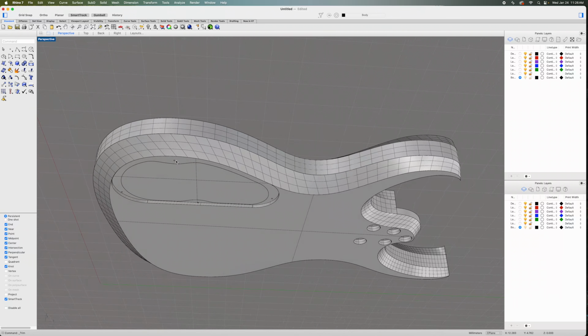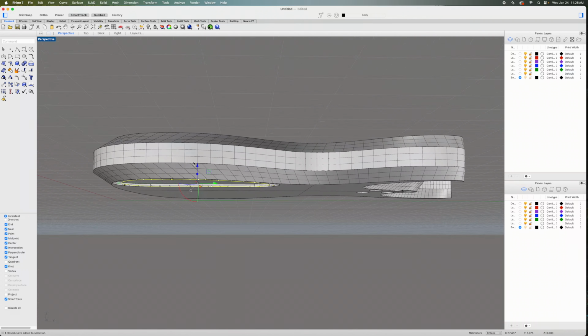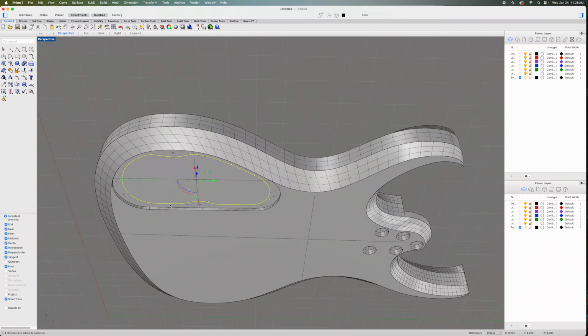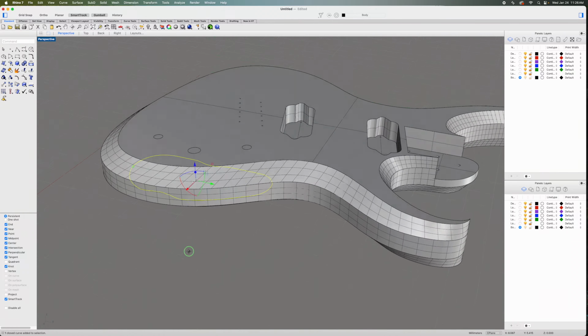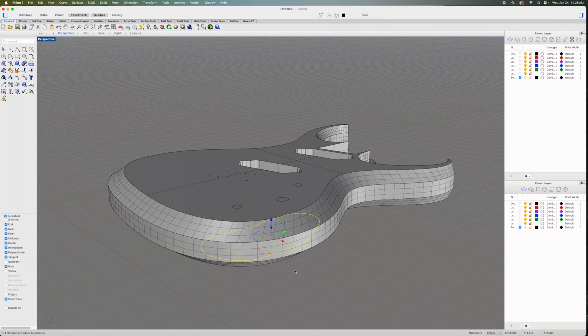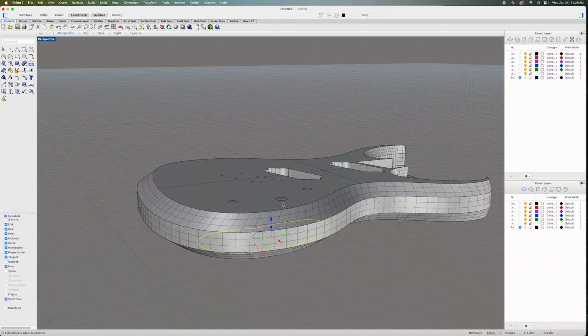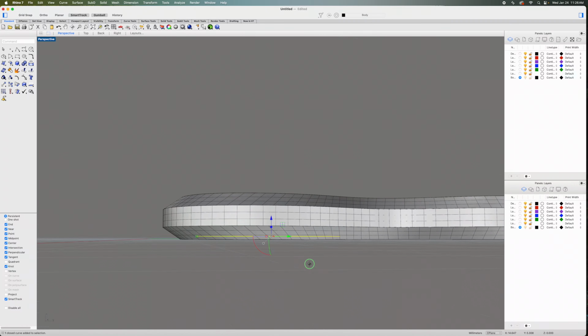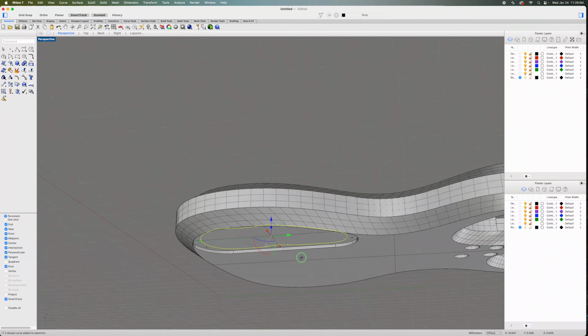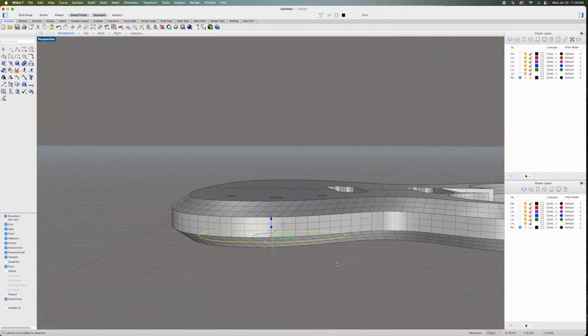So now what I need to do is select the elements and then raise those up 0.125 inches. Now I'm going to select this element, and I have to extrude it straight up to a depth that places the bottom of the cavity just below the surface, about 1/8 of an inch below the surface. So I've already raised that element up 1/8 of an inch. So I have to subtract 1/8 of an inch from 1.75, which is 1.625. Then I need to subtract another 1/8 of an inch, which represents the thickness of the top. So it becomes 1.5 inches.